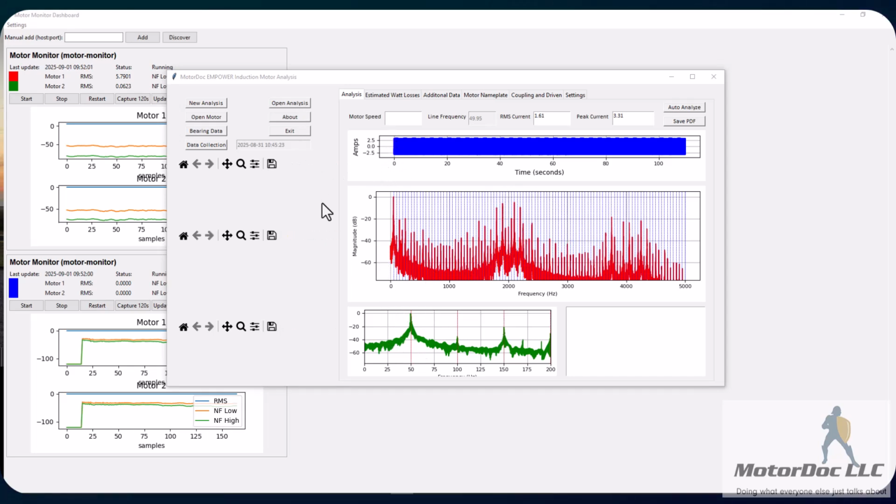There's the stuff there. It's all based on, this should be the actual. Let's go ahead and have it analyze that data for me. It's going in now and selecting the running speed and a bunch of other stuff for me. It's going to do its best, seeing as the line frequency is varying quite a bit and there's a lot of noise present.